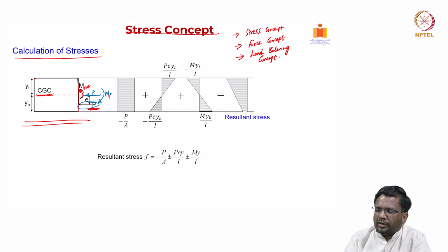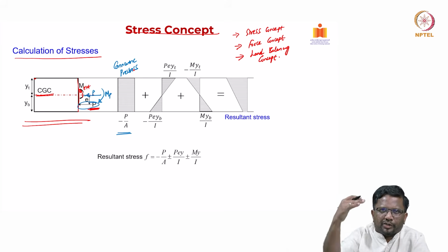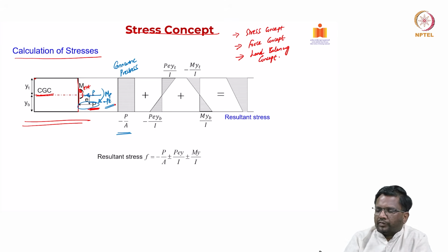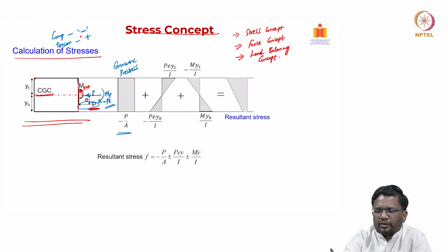So, you have load from concentric pre-stress, because we have moved that, converted into an equivalent load. Now, P is at the middle. In addition to that, the equivalent load MP, which is nothing but P into e. So, we have taken compression to be negative and tension to be positive, right. So, these are the sign conventions.